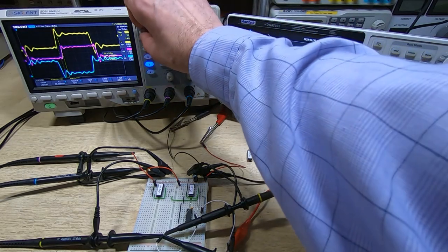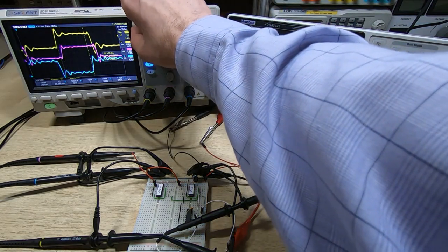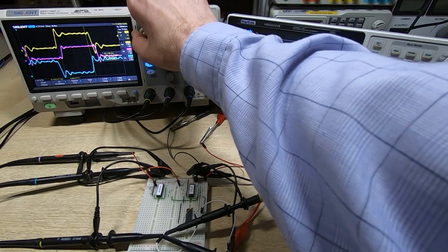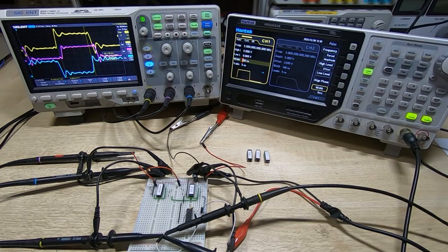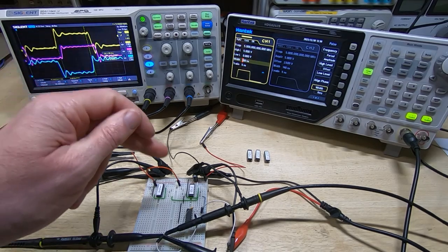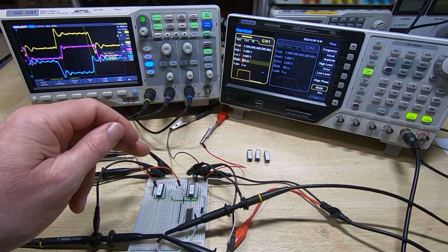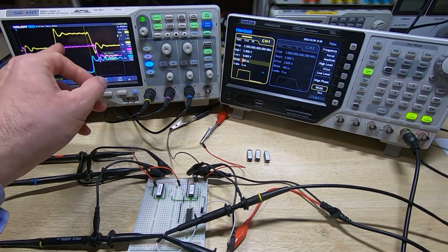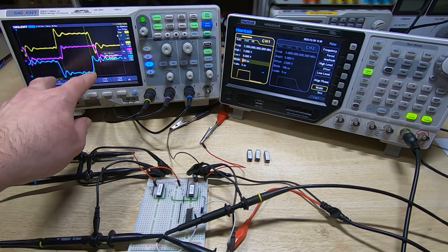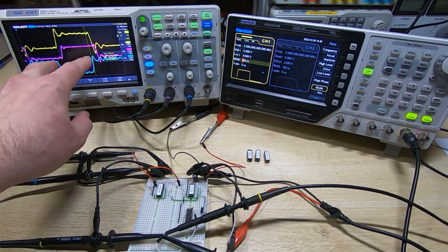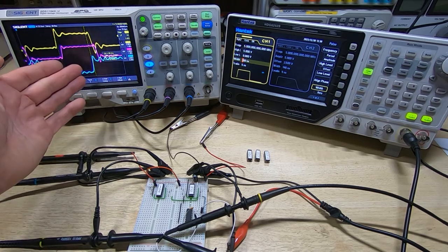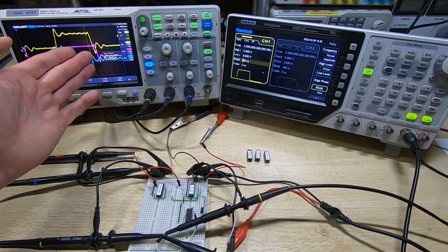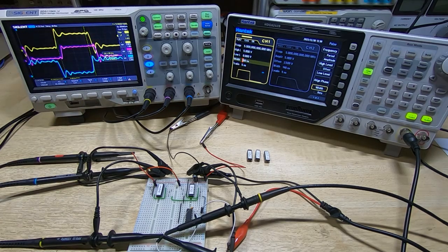And in fact, if we move the cursor across, then that's 90 nanoseconds. So it's more than 10 times the delay, and these are the same type of chip, remember, so very significant. And because we're getting so close to our 100 nanosecond limit, this is why this particular IC would cause an issue in a circuit, because the next event is about to start within the board. And this is just at 5 megahertz.